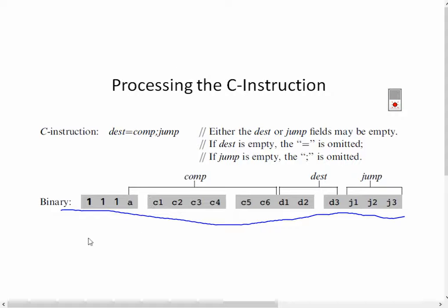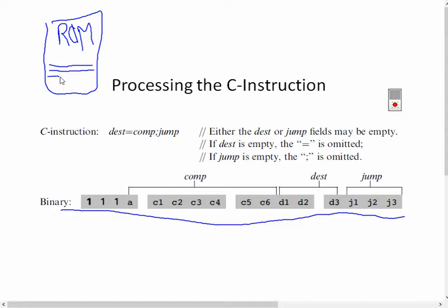And essentially what this is referring to is I have some memory unit out here. So in this case, it's going to be ROM, right? And that ROM is structured to have 16 1-bit memory cells that come together to form a word. And these words are organized into a long list forming the memory. Now we're calling it ROM, but it has essentially the same structure as the RAM. But I have these 16-bit words, which just means 16 bits, ones or zeros, on or off, and these form the instructions.